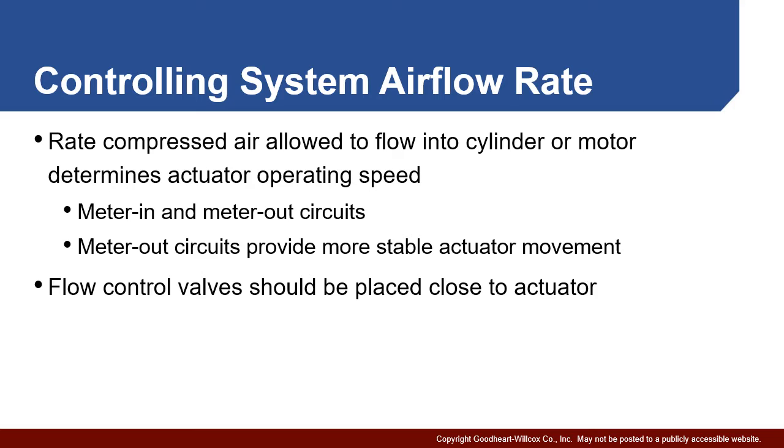To do this, we need to put a flow control valve, and keep in mind we want to keep it pretty close to the actuator. Anytime you put a distance in, that's a chunk of air that is compressible, so essentially can act like a spring. So by keeping the valves very close to the actuator, you have less of that springiness due to the compressibility of fluid.